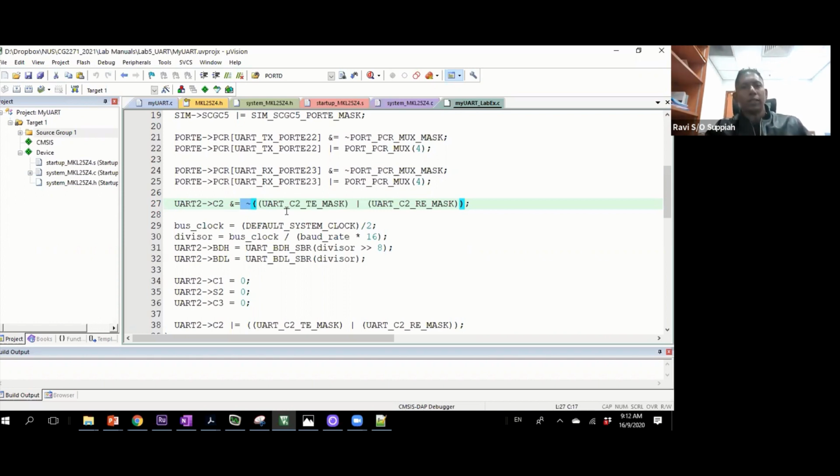Why I say that is because in general, when you work in group projects, someone else's code may interfere with your code, because they may have made some assumptions and accidentally written to some registers that you are also going to write to. So it's always good to do it in the proper sequence for your own particular module you're working on.